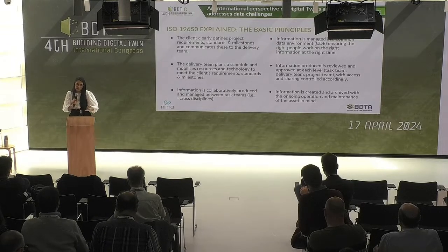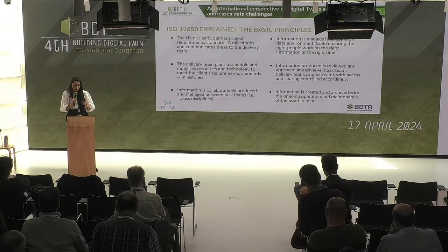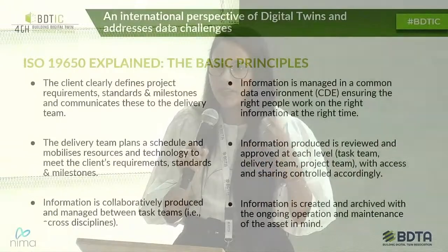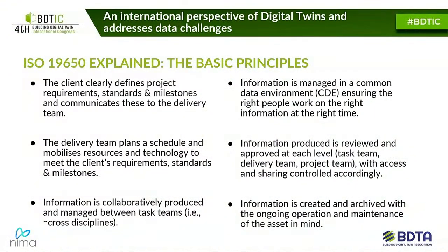Also, the standards have specific guidelines for standardization and classification of data within BIM processes, in this case. So naming conventions and the state of the information, that is also something that we struggle with. Is the information updated, and if it's not updated, where is it going to be located? This is one of the best things that this standard proposes: how to manage the state of each piece of information.